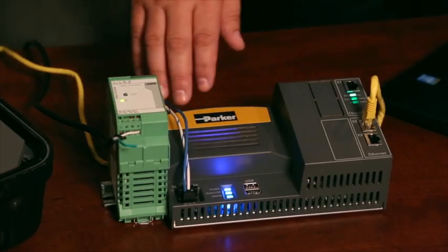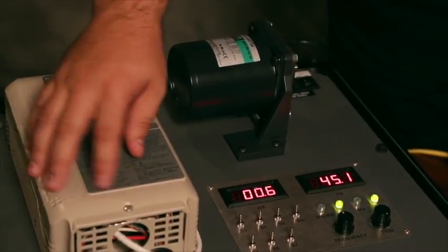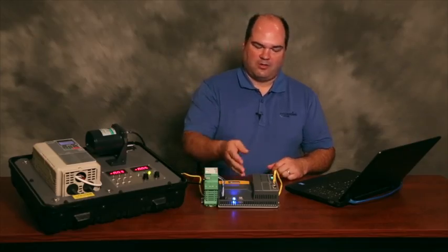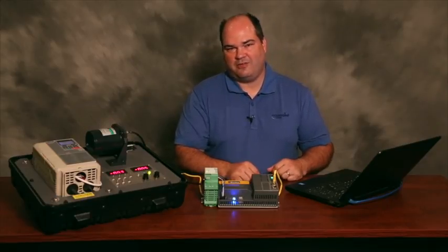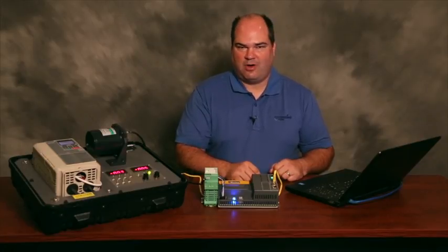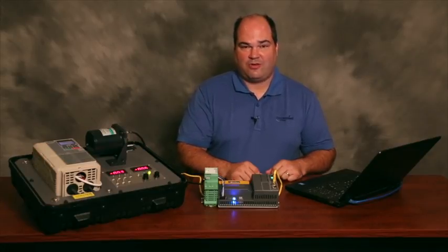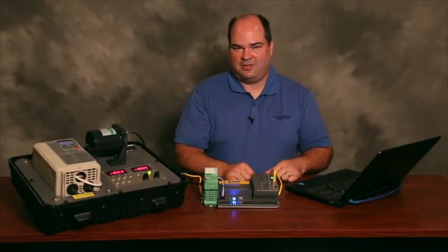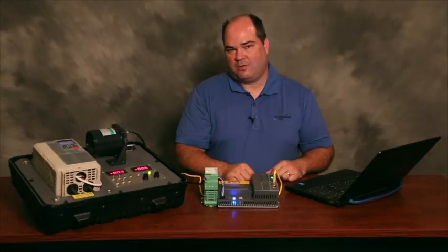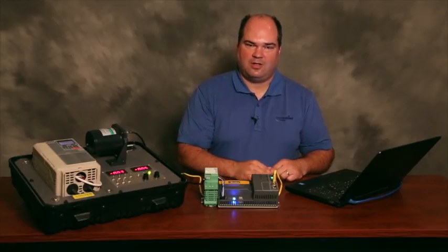Today we're going to talk about Parker's new Parker Automation Controller, or PAC, working with a Yaskawa A1000 VFD over the Modbus TCP protocol. Parker's new automation controller, PAC, is a machine automation controller that utilizes the IEC 61131 programming standards, PLC Open motion block standards, and the EtherCAT network for motion and high-speed I/O. It also has built-in TCP functionality for Modbus TCP communications to external devices like VFDs or a little slower speed